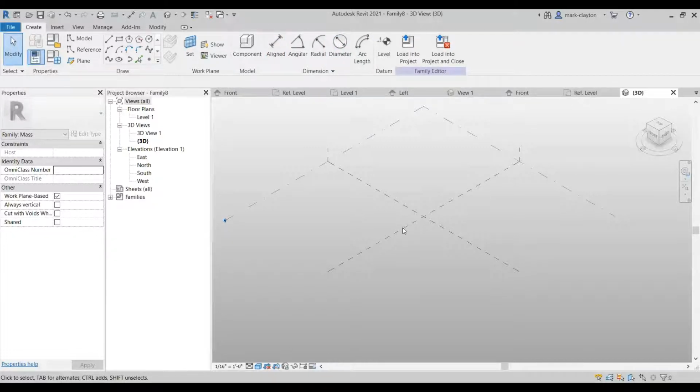When I first started using Revit, it was terribly confusing because it seemed like I would pick a command and the whole menus would change. Just remember, there are those three editors: project editor, family editor, conceptual mass editor. And realize they're each different.